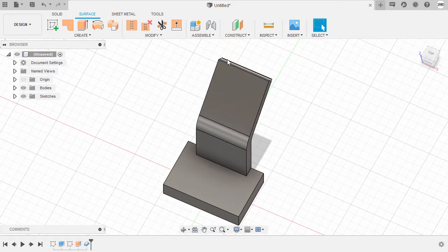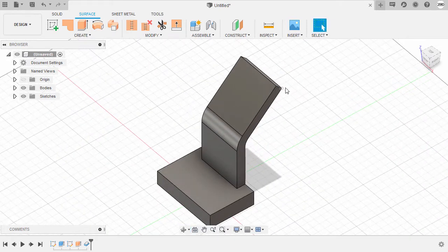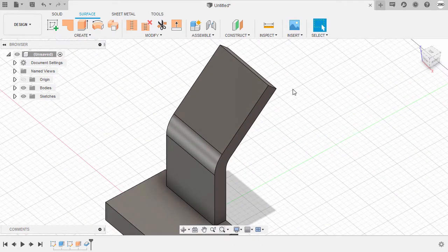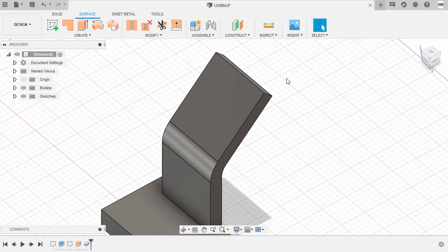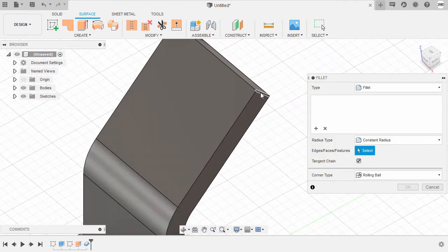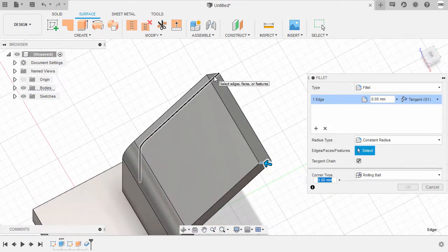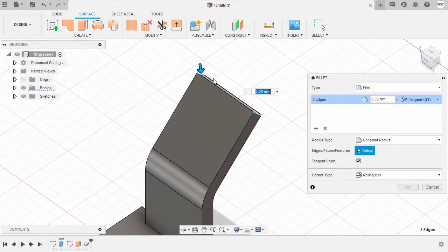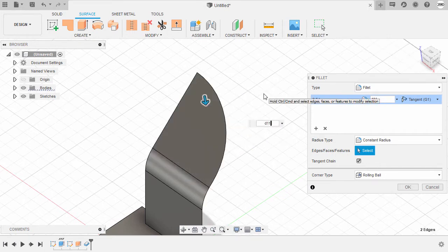Moving forward, let's turn this as a full round. So recall, the diameter or this distance is 64. Let's now hit F for fillet, selecting this edge and this edge. And from here, we're going to type in the D11 once more and divide this by 2.